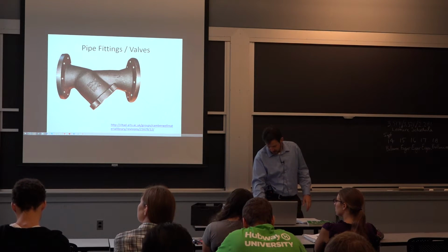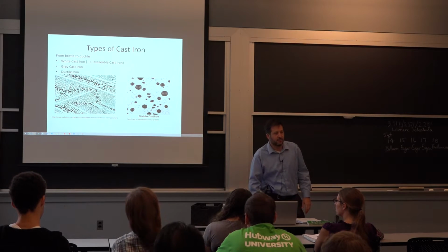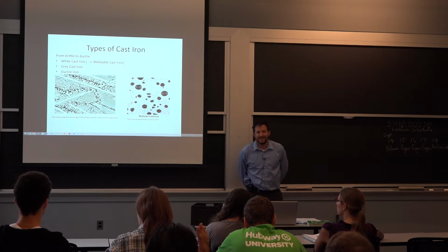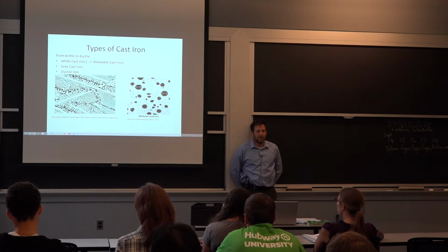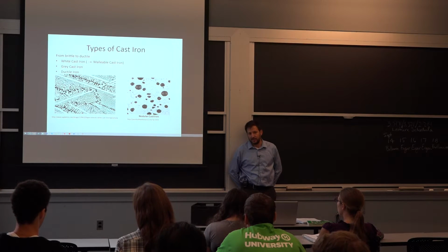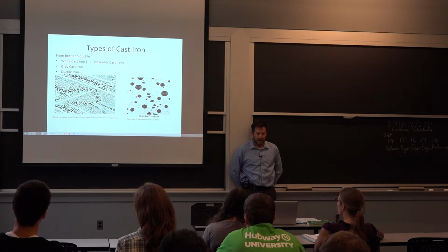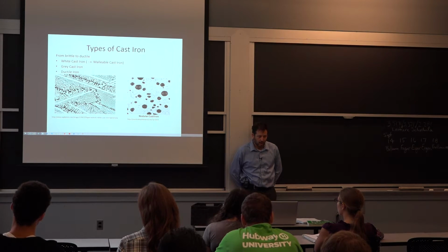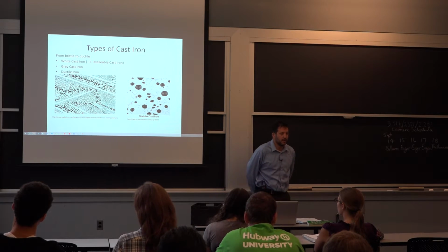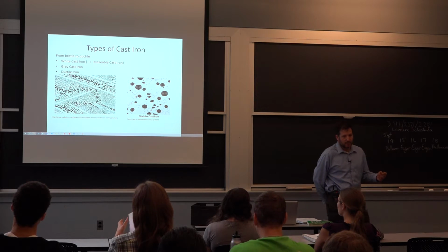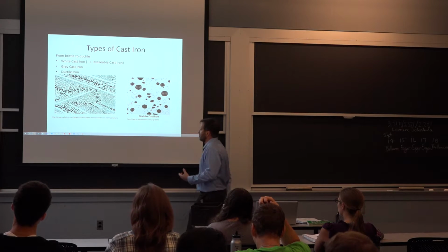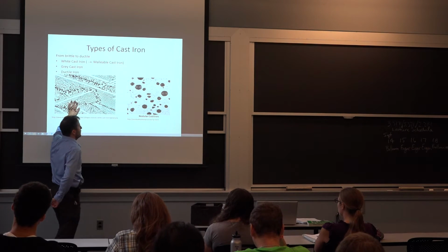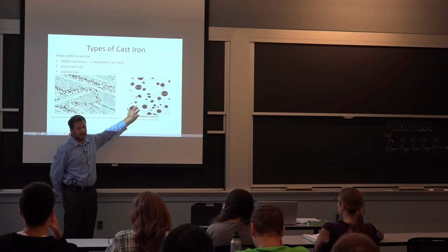Now, who thinks the cast iron is brittle? Yes, it is. Now, I do want everyone to remember that it doesn't have to be. So it's not because you're casting iron that you are left with a low ductility. There are small changes in composition and heat treatment you can make to change the internal microstructure from something that cannot really be deformed to something that is readily deformable.